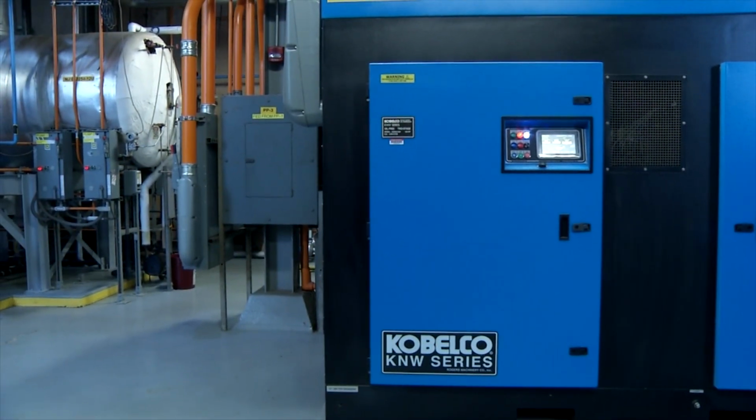But since you have 2 or more, how do you operate them the most efficiently? If they're of the same size and age, you can alternate which compressor serves the main load. One week use one, then the next week use the other, and this way they will age evenly and will need maintenance at the same time. Other times you just have an old compressor that's there as the backup, and you operate your newest machine all the time, using the old one in an emergency.